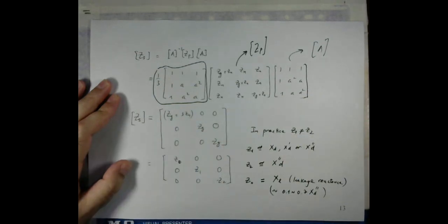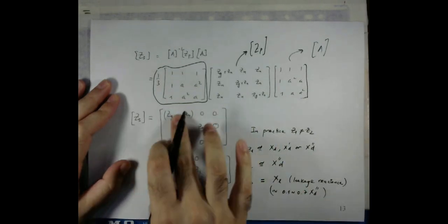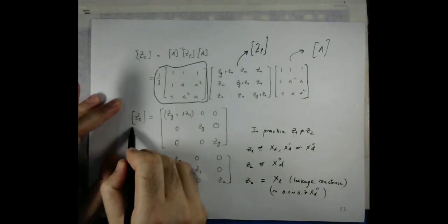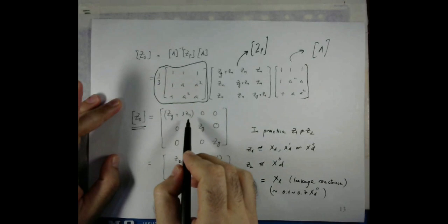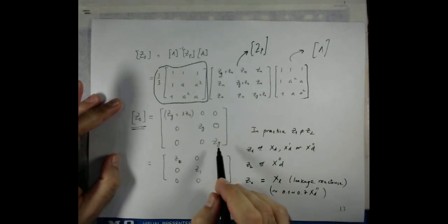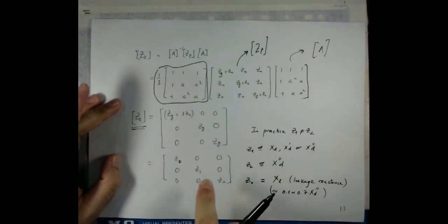Once again, I don't need to go into each step, but rather I am writing the final matrix, which is the sequence impedance, equal to Zg plus 3Zn. And if you remember, this is exactly the same as what we discussed for the case of the Y connected loads, when we consider also the connection of the neutral point to the ground via this impedance Zn.